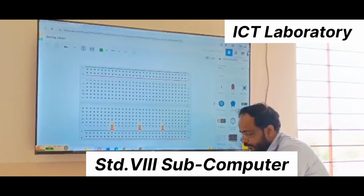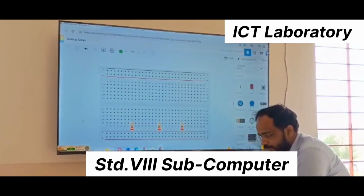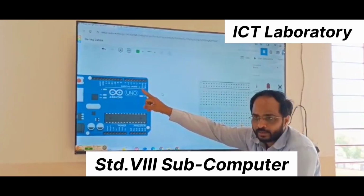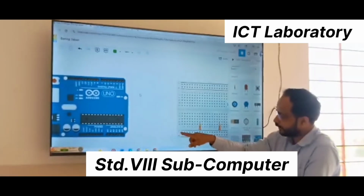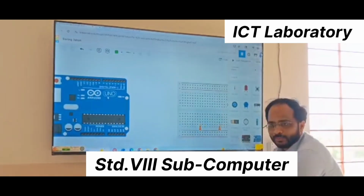Don't get confused with this numbering on the breadboard. Because our concern is to do the connections, and coding also we are doing for Arduino only. So we are concerned about these numbers. So you can place your resistors anywhere on the breadboard. Only the condition is one terminal must be placed on this line, the second one. Because we have to attach this negative terminal.